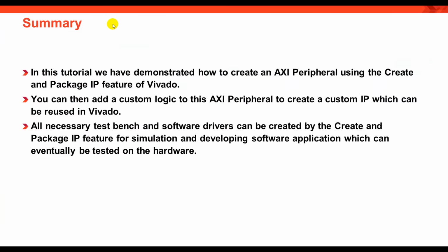So in this quick take video, we have created a new AXI peripheral, simulated it using an AXI bus functional model, and then verified its functionality on the KC705 board in a MicroBlaze-based design. We have seen how the Create and Package IP functionality in Vivado allows you to create a master or a slave AXI peripheral, which can be used to create a custom IP.